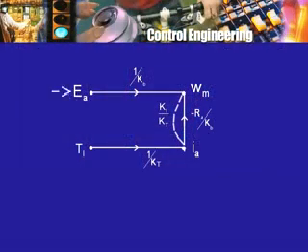So that is one thing that we have to first of all work out. Find out all the paths from an input node that we are looking at to the other node that we are looking at. In this case, I want to have an expression or a part of an expression for omega m in terms of EA. So I am concentrating on EA as the input node and omega m as the node for which I want to write down an expression. In this case, there is only one path. But of course, in a very complex signal flow graph with a large number of nodes, with large number of transmittances connected in various ways, there could be more than one forward path.